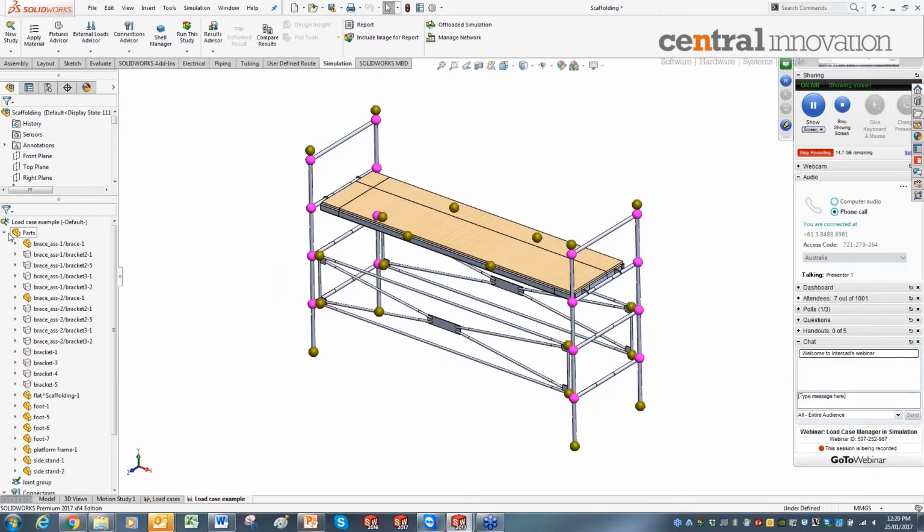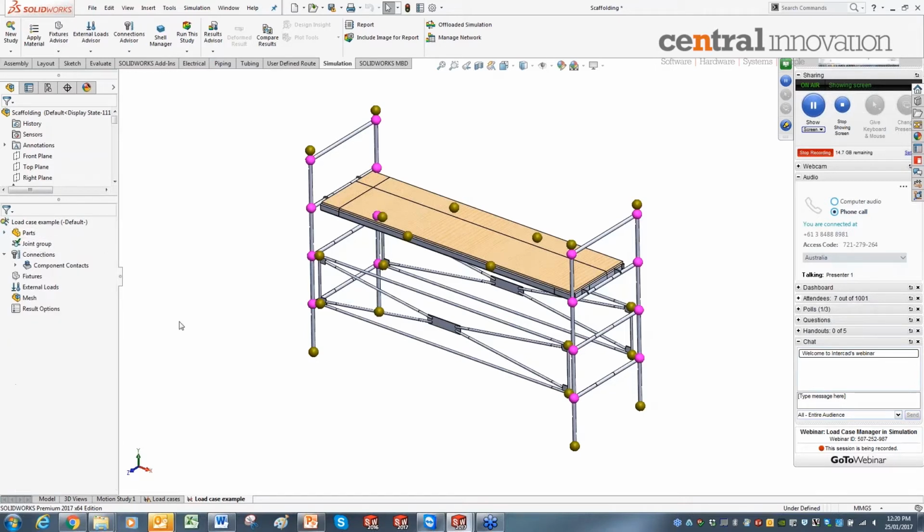And I'm going to use the same material, one of the steels. I don't want to manually apply it for all the components, and I don't want to define the element type manually for all the components. Instead, I'm going to copy and paste it, or I can simply drag and drop. As you can see, I'm activating the predefined study in here, the first simulation study. Once I activate it, I can copy and paste it.